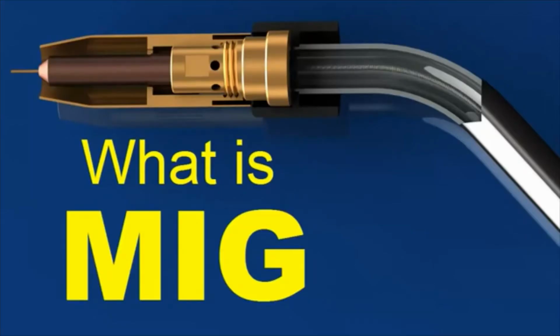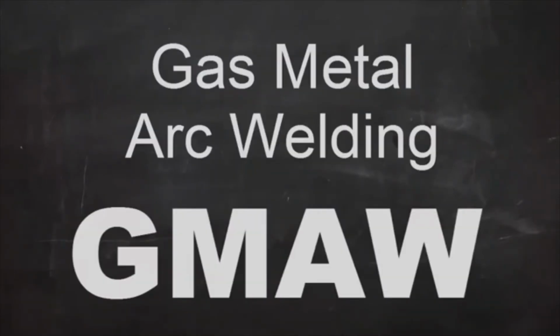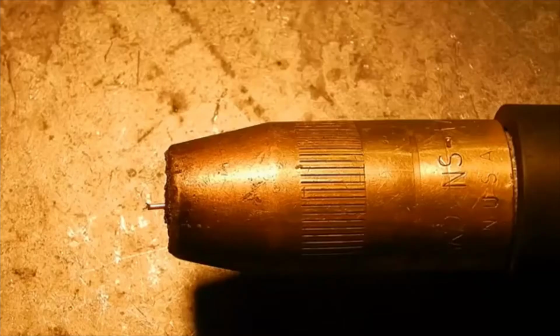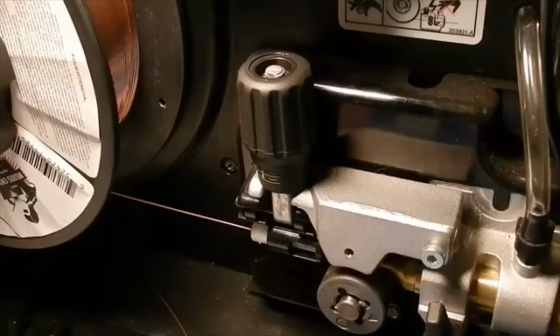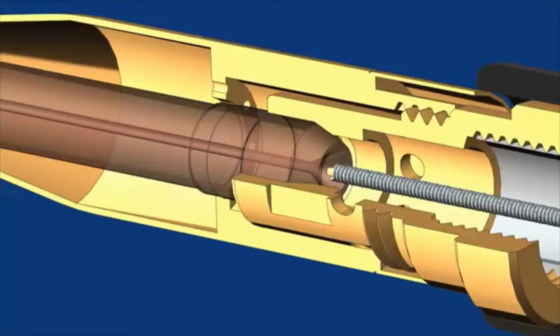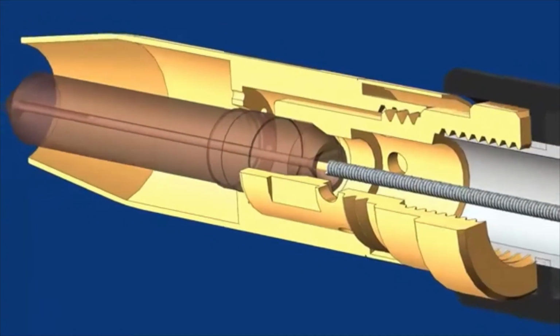What is MIG welding? MIG stands for Metal Inert Gas Welding. The American Welding Society calls this process gas metal arc welding, or GMAW. You might also hear it called wire welding. In MIG welding, a thin wire acts as the electrode. This wire is fed from a spool mounted on a gun or inside the welding machine through a flexible tube and out of the nozzle on the welding gun or torch.